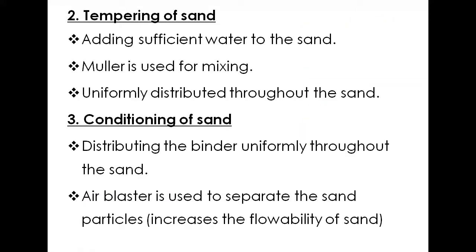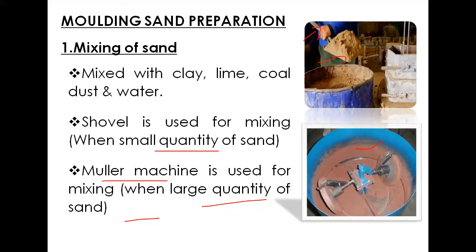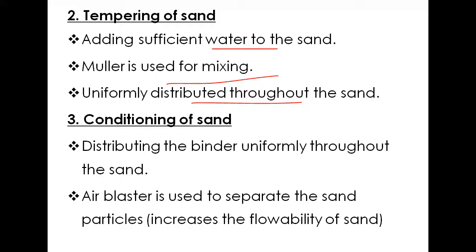Next one, tempering of sand, adding sufficient water to the sand. The muller is used for mixing, so that water is uniformly distributed throughout the sand. Compared to manual mixing, muller machines help mix throughout the sand, so uniform distribution occurs in this operation.